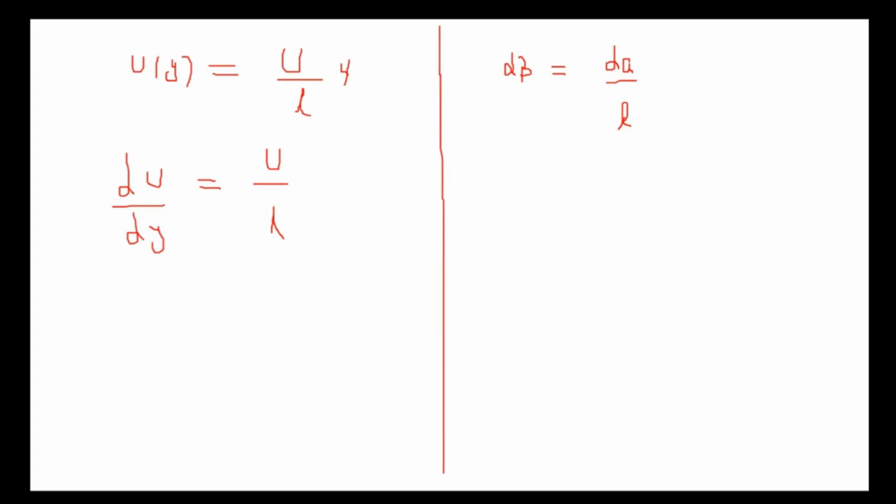On the other side, what we do is we need to calculate the rate of angular deformation, that is, how the angle beta will change with time; rate is with respect to unit time. We also know that the top plate is moving. So the distance, how much distance will be covered in how much time? Distance is velocity into time.